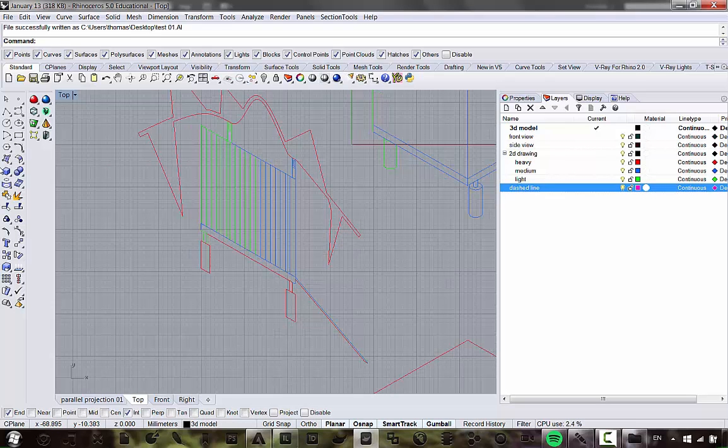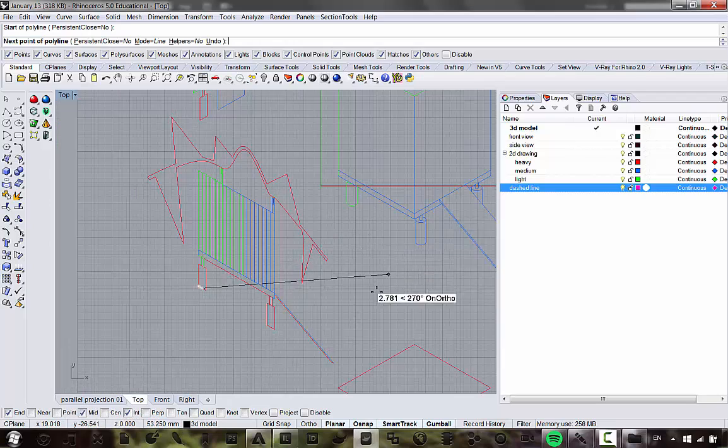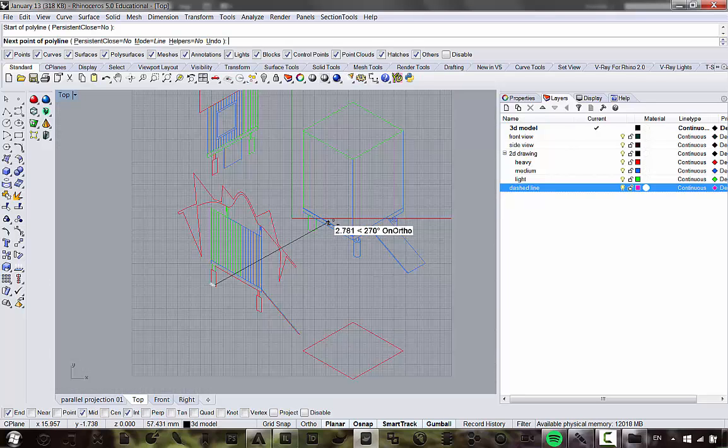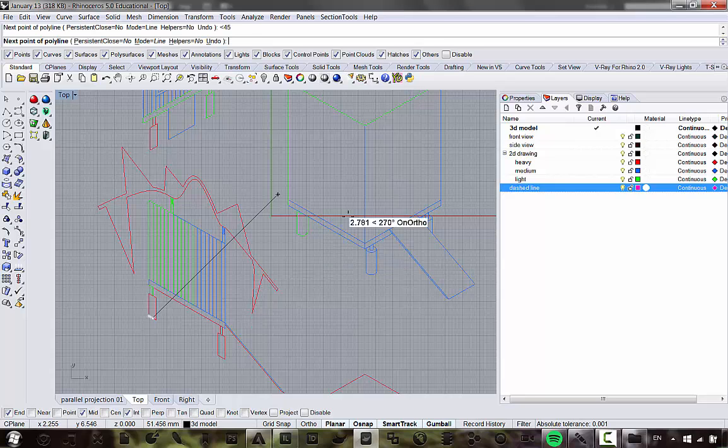We're just going to draw some lines going from maybe these midpoints here. We know that since this is a 45-45, essentially what we're going to do is just snap to 45. So that's a left angle bracket 45, and, oh, apparently it's not. Maybe it's 30 degrees. Yeah, it's 30 degrees. So we're going to snap to 30 degrees, like so.